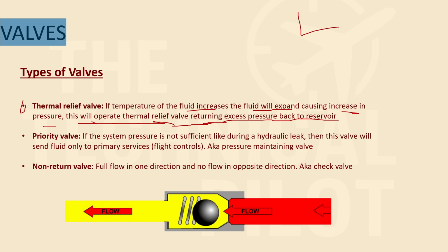The thermal valve will be attached somewhere here, and if there is a temperature increase for any reason, the valve will sense that and send the fluid back to the reservoir. As the name suggests, whenever there is heat, it will relieve the pressure and send the fluid back to the reservoir.